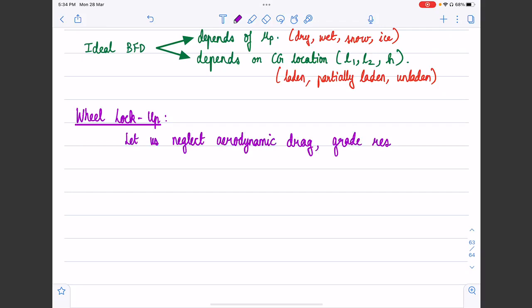These numbers are going to be typically smaller when compared to the magnitude of the brake force, particularly at the peak levels. So we essentially neglect all these other loads, and we consider only the braking force. In fact, some people will also neglect the rolling resistance, since that is also small. But let's keep rolling resistance for the time being.